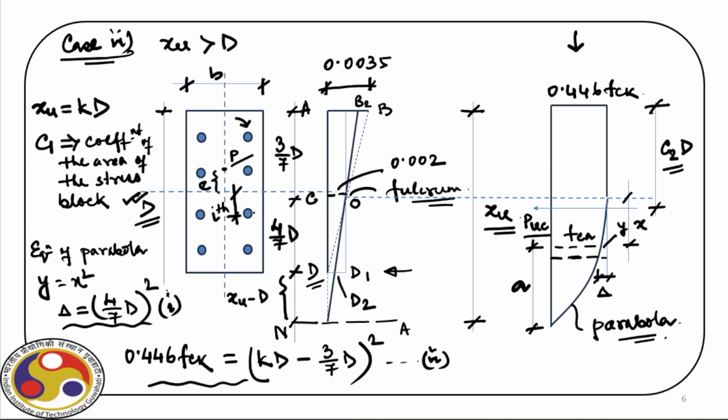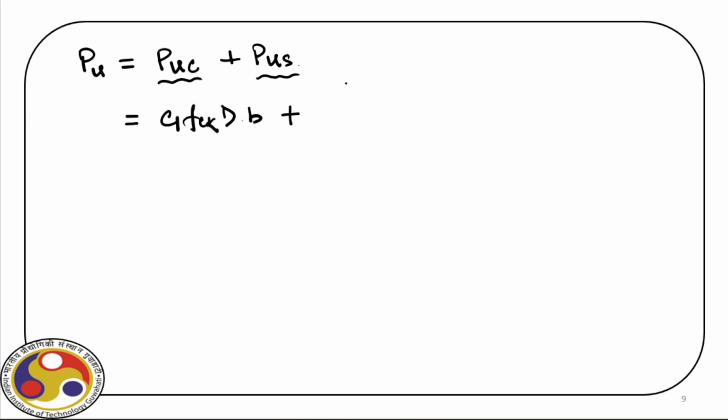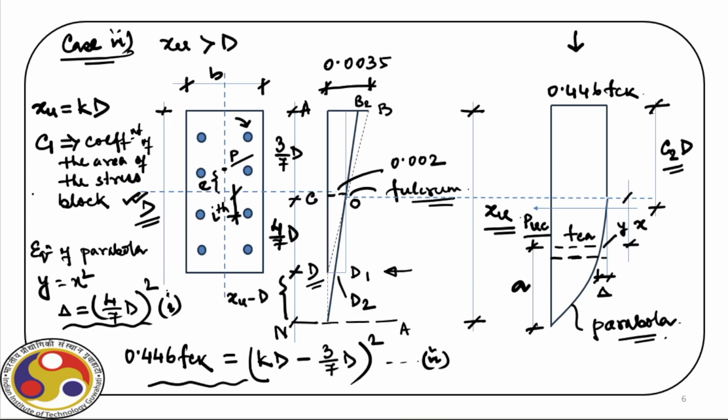as the stress in the steel rebar, and the surrounding concrete will also have stress. So the difference of that stress is the net effective stress acting on these bars. So for that we have i equal to 1 to n, we can have n number of rebars. So the ith row will have Pi, that is the percentage reinforcement, times BD divided by 100. So that is the area of the rebar at the ith layer.